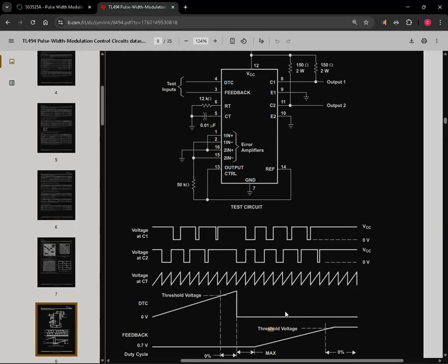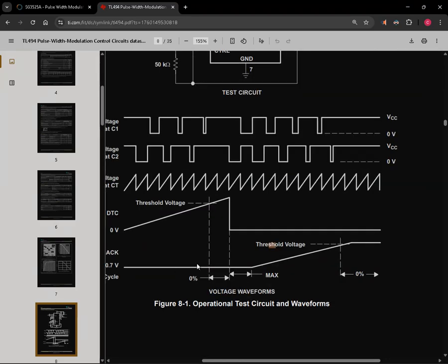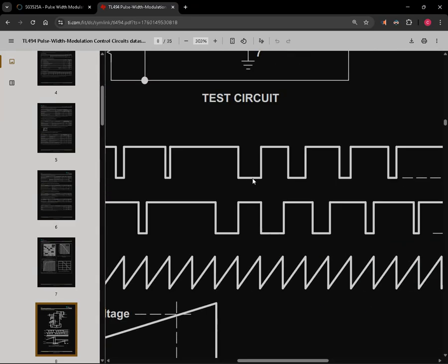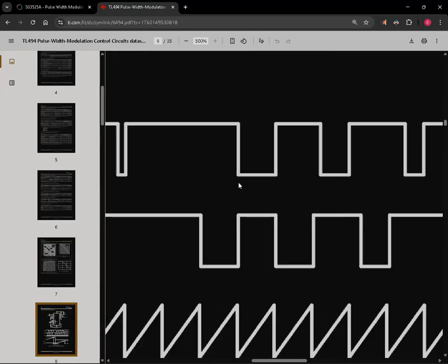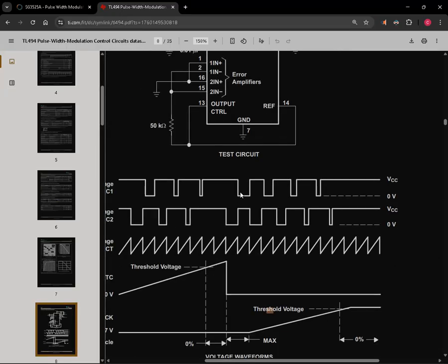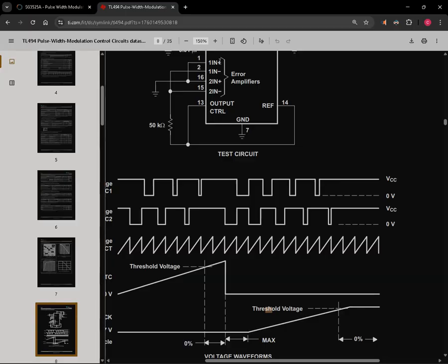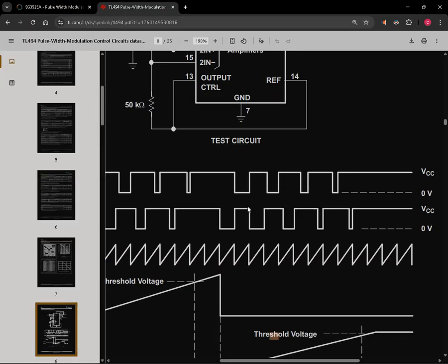Now we have other controls here, right? So we have feedback. In this region over here, we have zero feedback, and we have that here. So this is where you're seeing perfect, but they have a little dead time over here that won't cause the MOSFET to blow out, right? You could barely see it, but it exists here, we can't zoom in much to see it, right? So in this region over here, we have no DTC and no feedback from the error amplifiers, right? So the error amplifier, we have no feedback coming to it. So we see the exact 180 degrees, no additional dead time control.